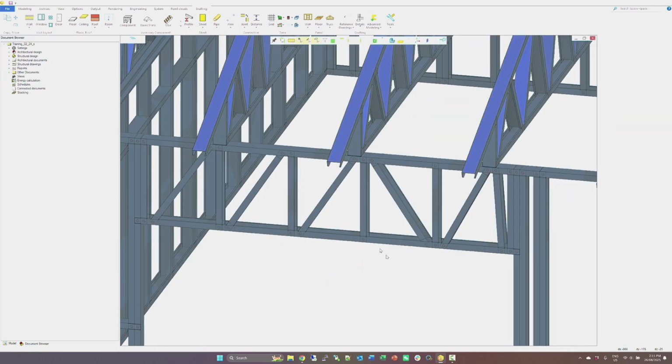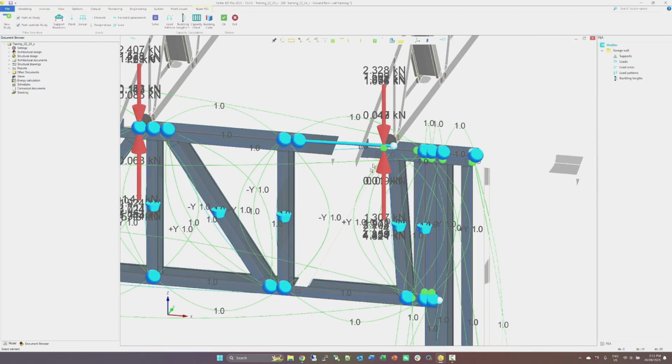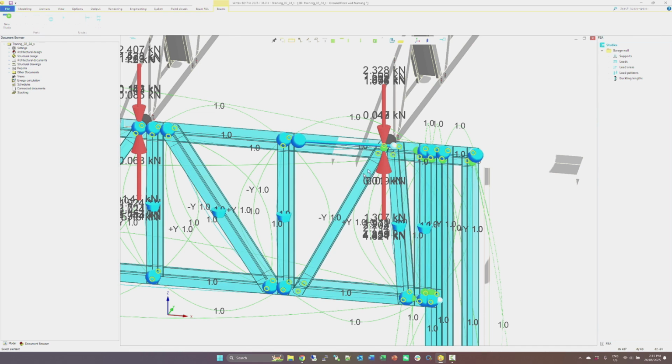Go back to FEA module now. As you can see, the new profile is not included in the current FEA study, and the connection here will also be moved because the profile has been moved. Rather than establishing new contact, I'd rather just create a new study all over. I just have to name it a different name.